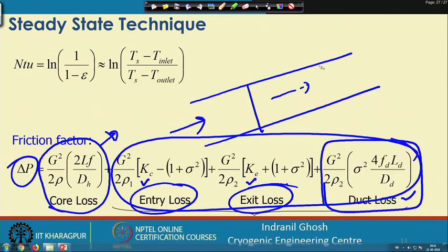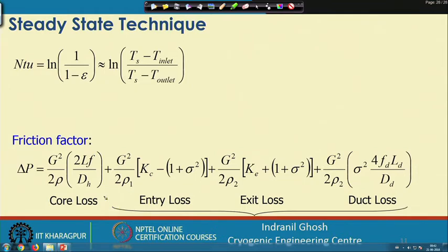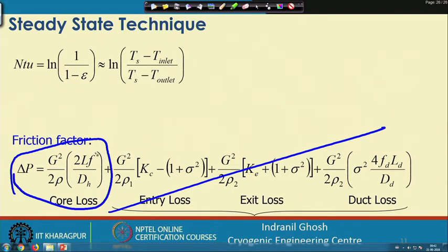We have the duct size known, and the friction factor of the rectangular or square duct will be known. From there we can estimate all these parameters, and calculate the friction factor corresponding to the pressure drop where we have the test surfaces. Basically, we measure the pressure drop and then calculate the friction factor using this relation. If we do not need that much accuracy, we can easily neglect this term, concentrate on this part, and find the friction factor from the pressure drop calculation.